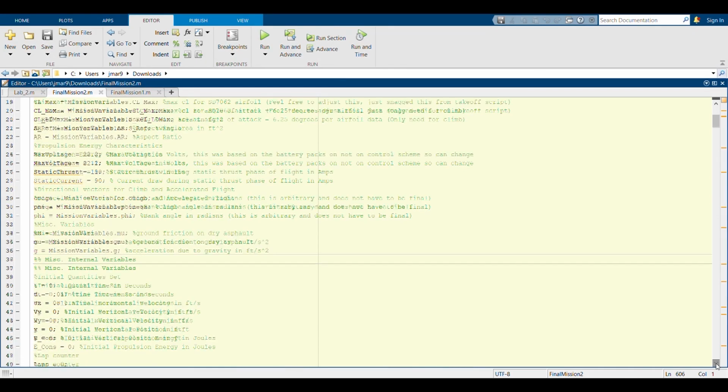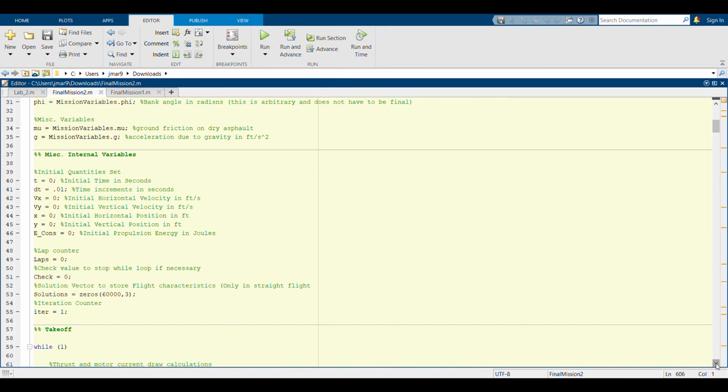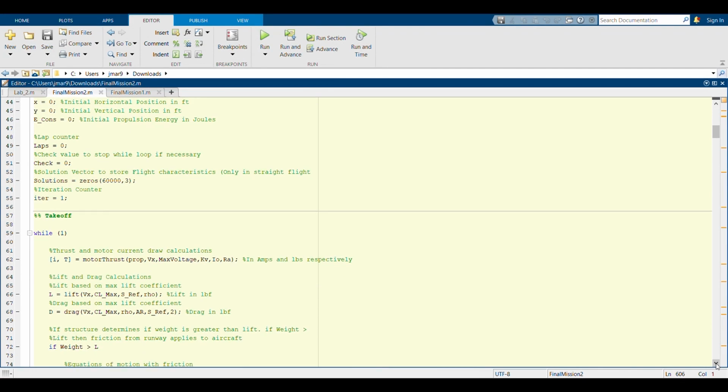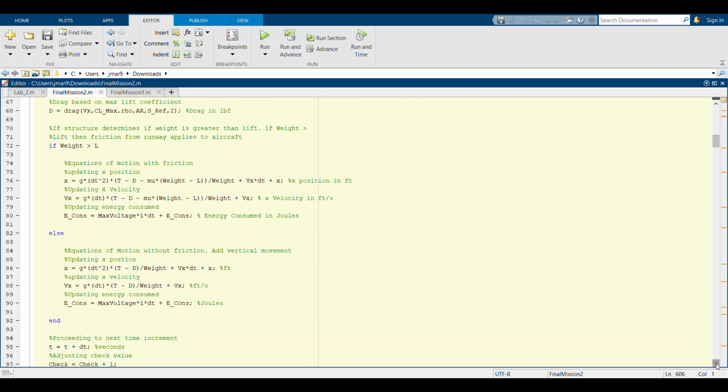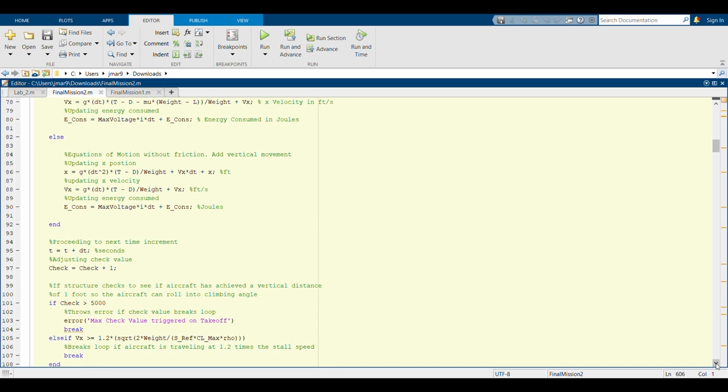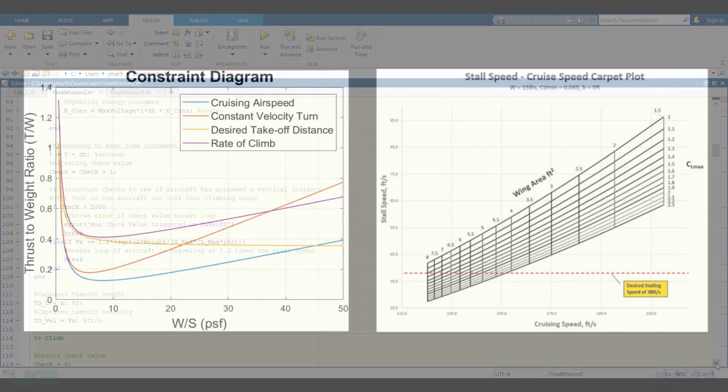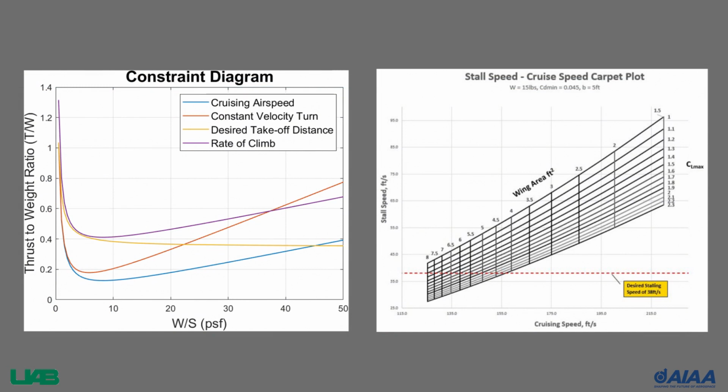When performing the scoring analysis, we determined that ground mission time and average lap time were the most influential score factors, followed by sensor weight and sensor length. Therefore, we optimized our plane to be fast and easy to load. We decided to use the maximum 5-foot wingspan to generate as much lift as possible.